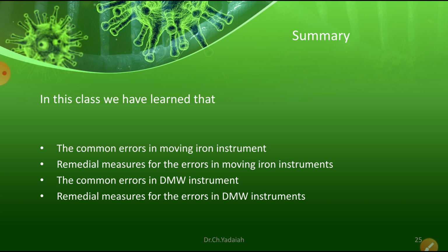Using jewel bearings to reduce friction, placing all equipment in dust proof covers, and using constant alpha materials, with constant change in resistance with temperature, we approximately keep the errors low. So these are some errors in our instruments generally used in laboratories, workshops or wherever we require.